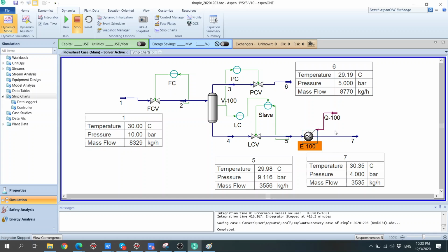Yeah, temperature changes because we specify 1 kilowatt. We put in 1 kilowatt, and then if we have a higher flow, that means this temperature will drop. If we have a lower flow, that means this temperature will go up. Yeah, it's m Cp delta T. Alright. Okay.